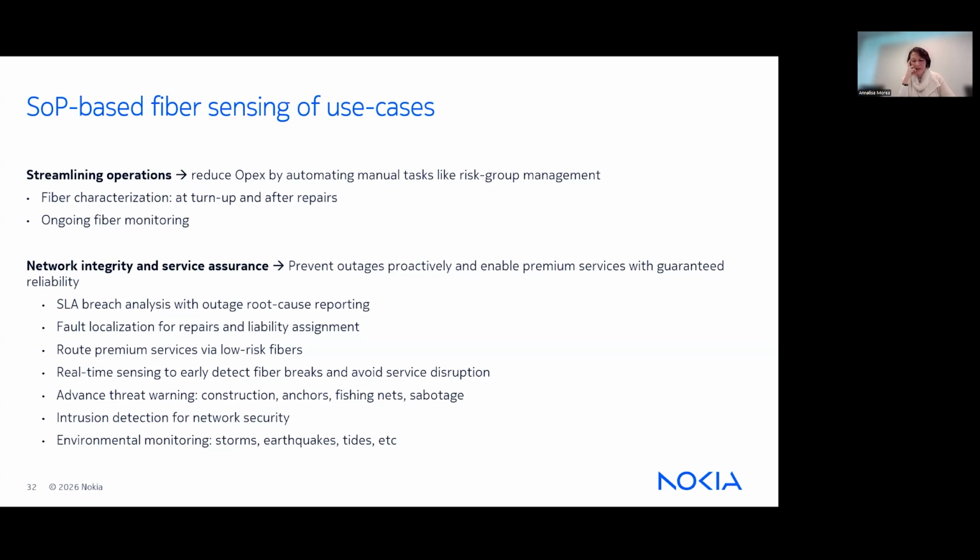And so we discovered that the feature of fiber sensing and also its labeling may help the operators in network operation by making some actions more automatic, like fiber characterization by detecting which parts of the fibers are aerial or submarine, then also trying to detect the SRLGs of some fibers, and also by detecting in the network which are the low or high risk fibers, and so by detecting these zones, trying to avoid high priority traffic passing through this area.